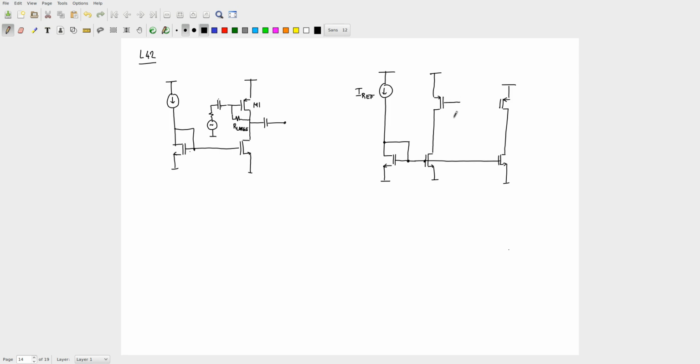And what should I do further? I am trying to make a current mirror. So, for this PMOS, I can connect its drain and gate. Okay, so that will set this value of source to gate voltage, and then I can use this to connect to this, right? That will be my biasing circuit.